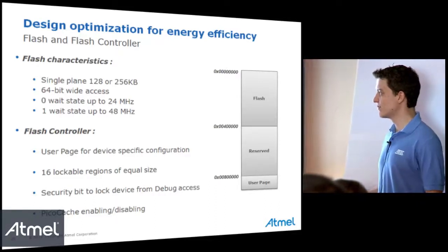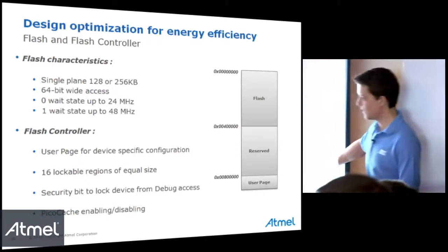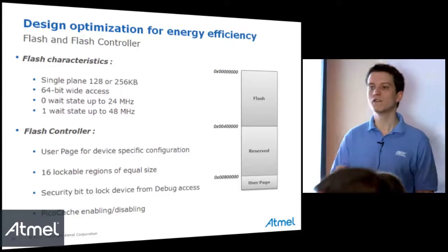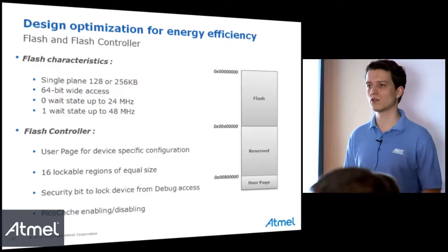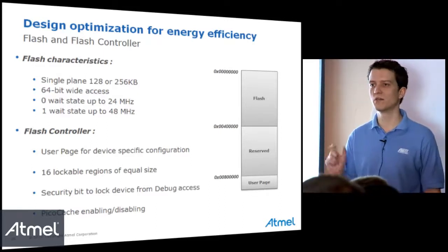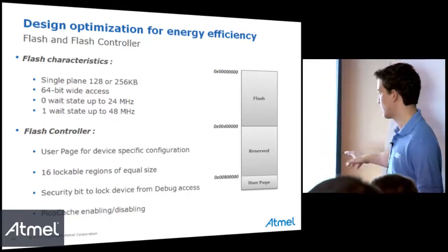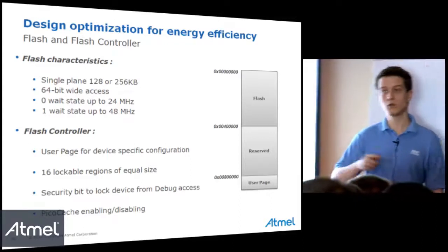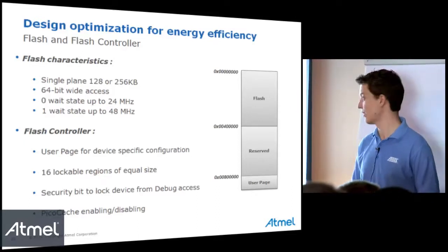We have an enhanced flash controller that allows you to modify what we call the user page. The user page is mainly a configuration page where you can store some settings, or even set some bits that enable specific features in the device. Usually you can find Watchdog, or also some configuration for Samba that we will see just after, or that you will use during the hands-on.